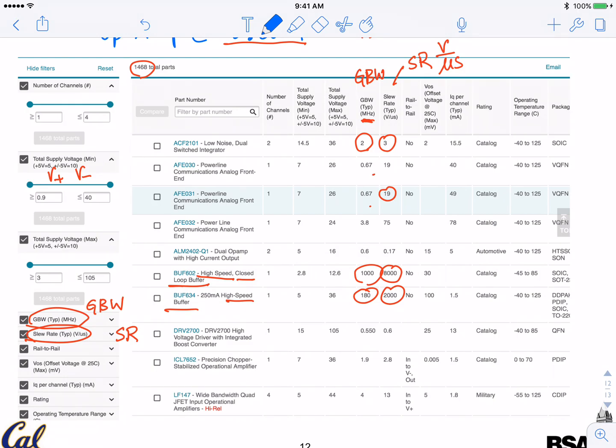The slew rate, if you look, here is kind of a summary table. If you go to the individual items, you will see slew rate, typical value, 1 volt per microsecond, maximum value, 2 volt per microsecond, minimum value. So there's a range there. It's not the same fixed constant for different chips. Yes? Can you explain again how the slew rate is related to the bandwidth?